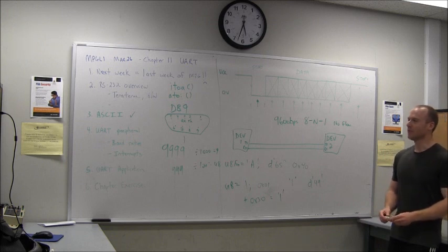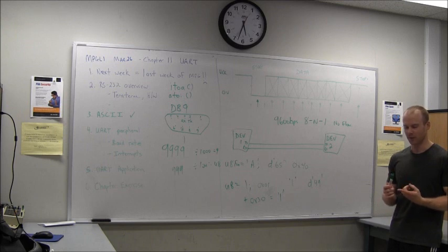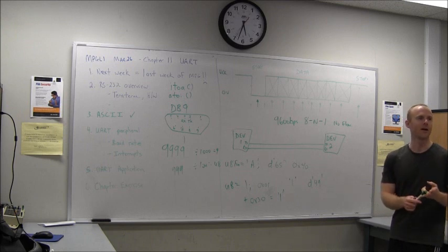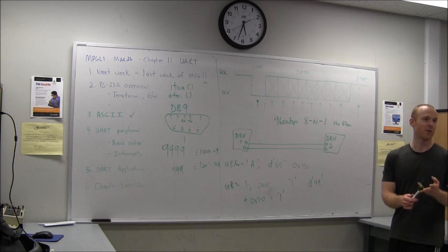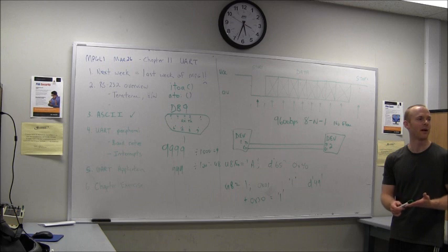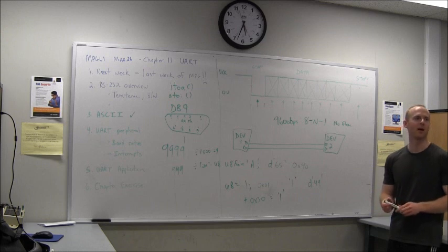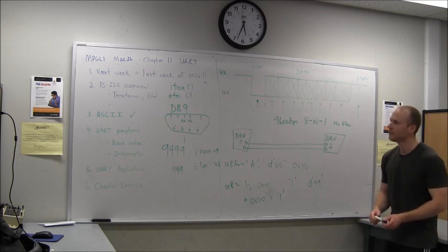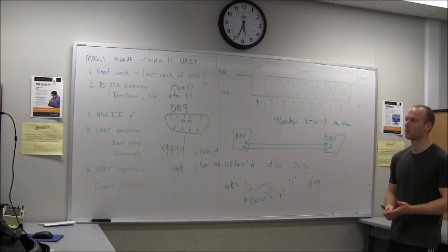The UART peripheral is pretty easy to use. So far, what peripherals have we done? We've done the PWM peripheral, we've done timer peripherals, GPIO is a peripheral, we've done that, and we've done interrupts. Every time we start one of these things, what do we do? Open the data sheet, read through it, figure out what registers we need to work with and what to set them up as. There's usually a couple things you need to spend a bit more time reading to figure out exactly. As far as the UART peripheral goes, pretty easy.